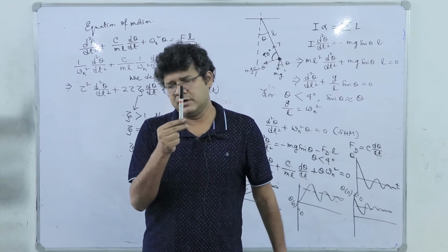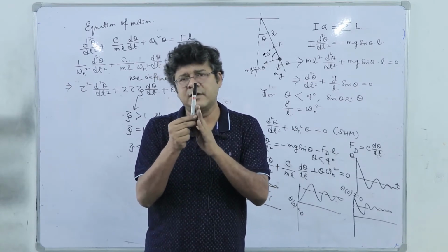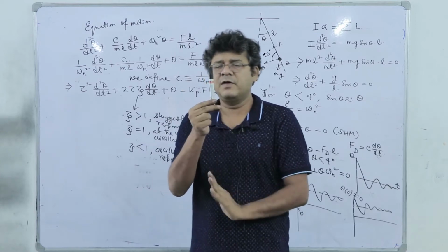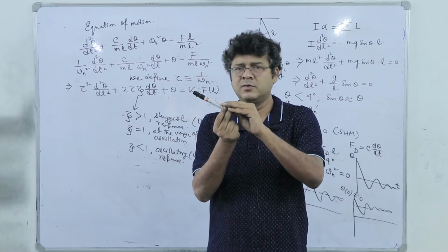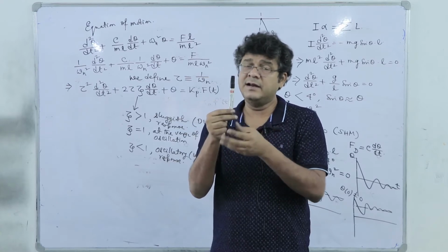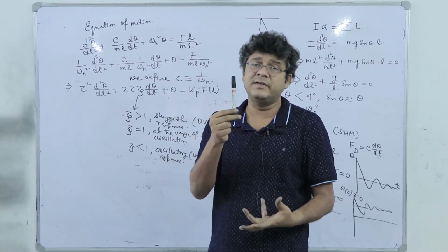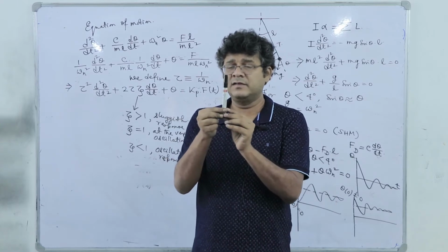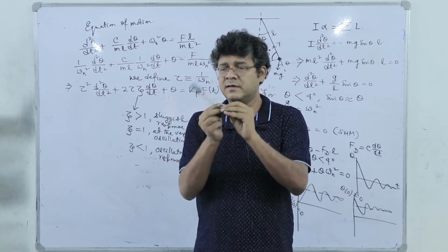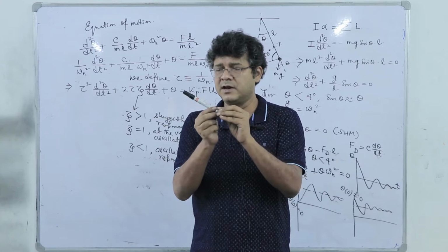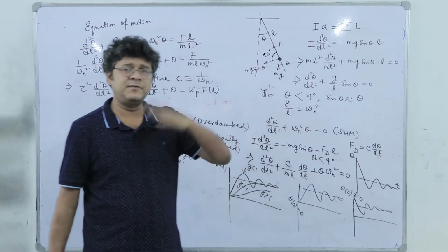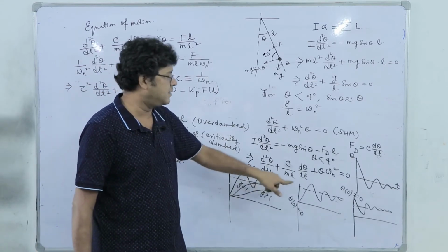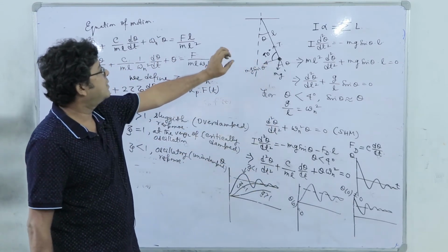But if it is at the verge of oscillation, what will happen? If I give the pressure, it will move like this and attain this 2 atmosphere. On the other hand, if we further increase the sensitivity of the spring, the situation will be something like this. It will oscillate about 2 atmosphere and finally settle to 2 atmosphere. So it will oscillate before settling, just like the pendulum, right.